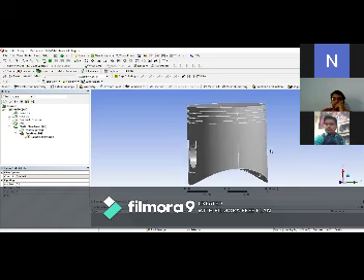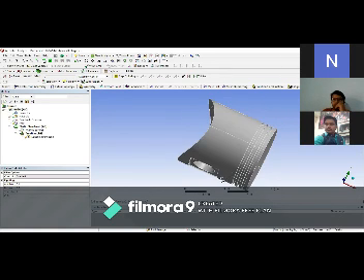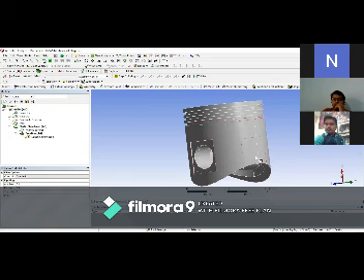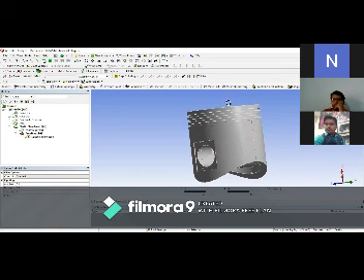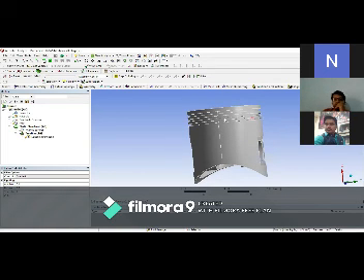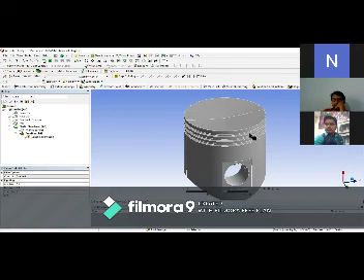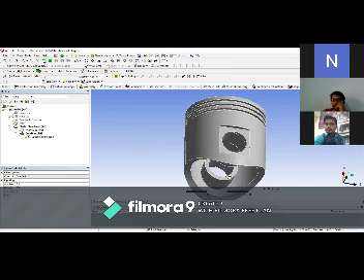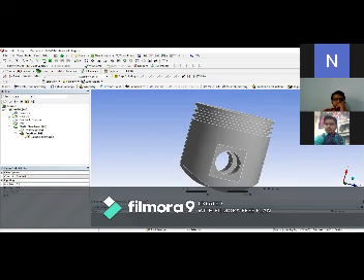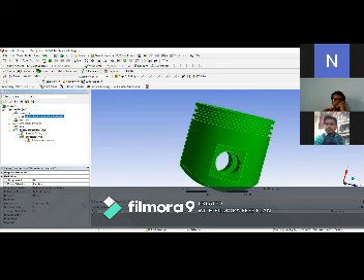Okay, so this is the piston model. This model was made in SolidWorks, and we saved this file as a STEP file, our piston model. This is the upper head, the crown of the piston, and here is the connecting rod place. Here we find the geometry, materials, meshing, static structural, and all these steps, and we clearly see that the piston is structural steel.